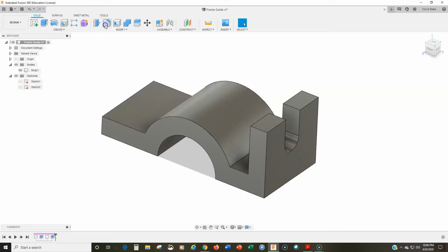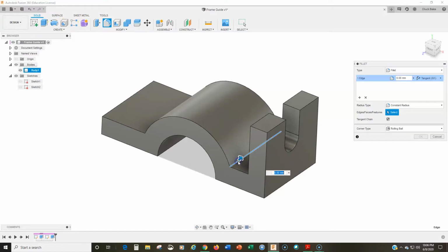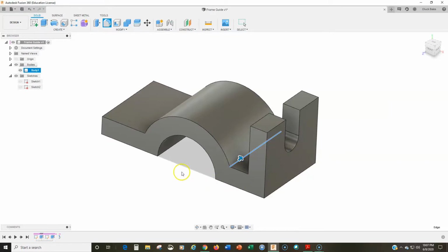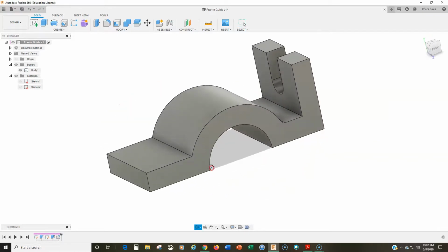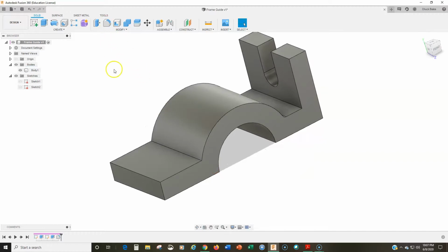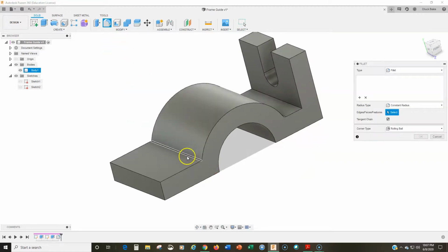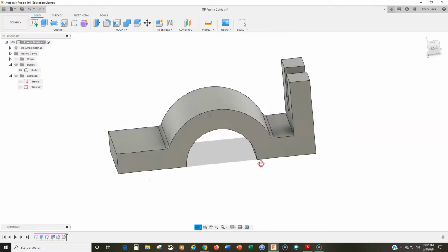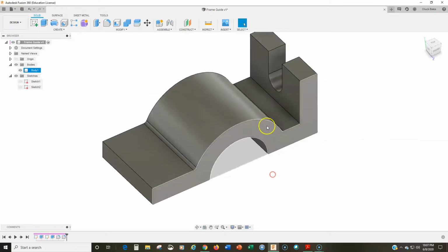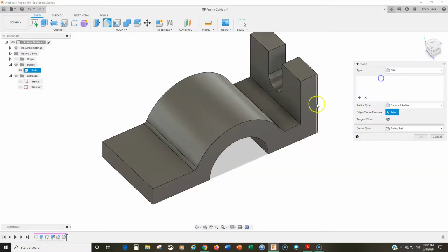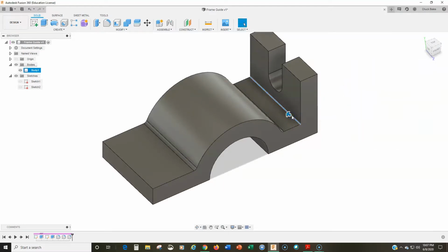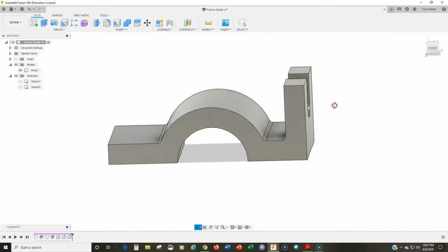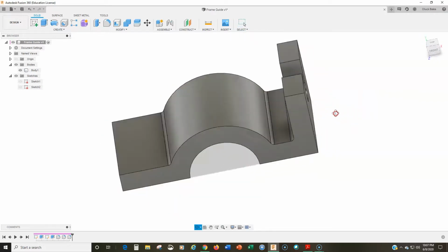So you have the fillets on this. And what is the fillet? The fillets are radius 2. Right, so you have fillets on all this. Let's go back here, repeat the fillet. We go with the radius of 2. Right, and we can do the same thing over here. Fillet with a radius of 2. And so on and so forth, right?